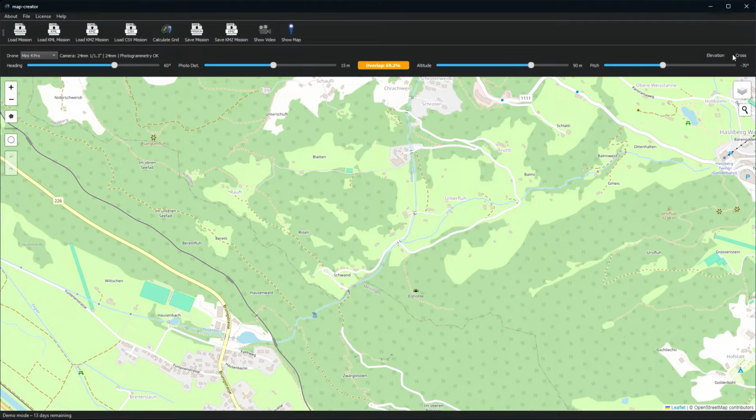The goal was to make an easy tool for photogrammetry and Gaussian splatting with also some advice and mission evaluation, so that's very easy to use and you get feedback if you have some problems with the mission. Actually, we can see we have an overlap of 69%, 70% is recommended, but I will show you later how we can optimize this. Let's first start with a Polygon mission.